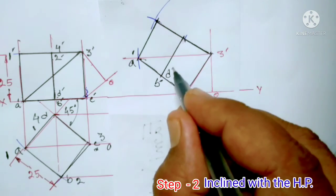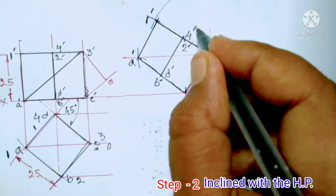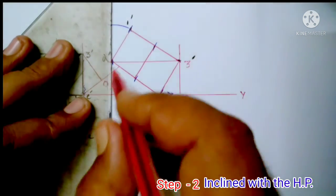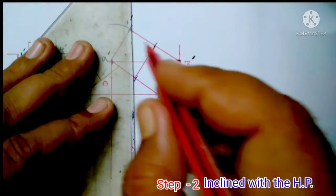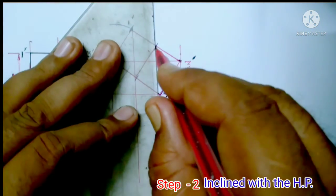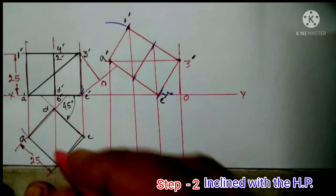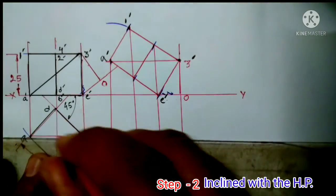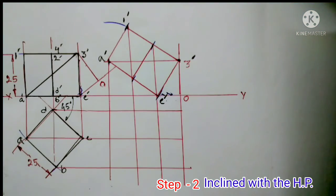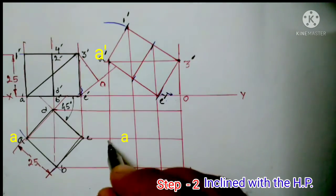After completing the drawing, give the name of each point. Now draw the projection line which is perpendicular along with the XY line. Now draw the projection line from the previous top view which will be parallel to the XY line. Mark the intersecting point between two projection lines for the same point of front view and top view.